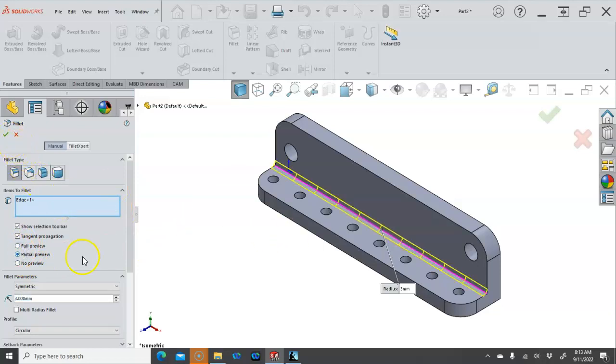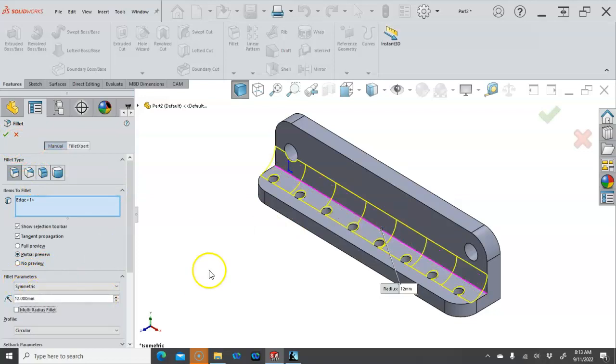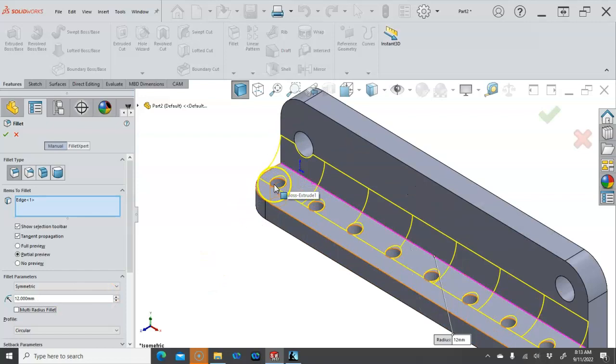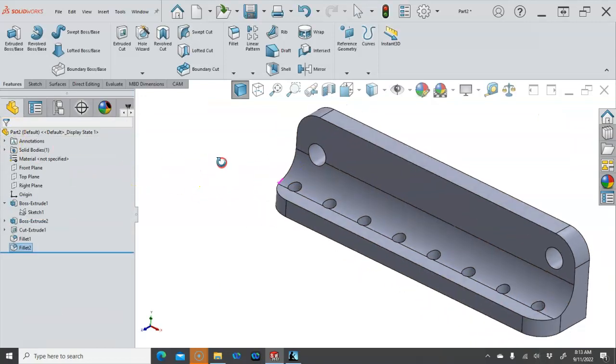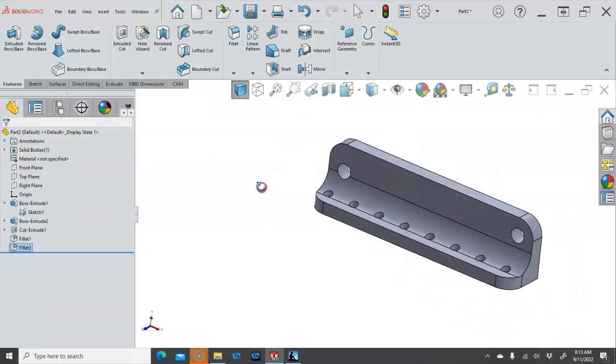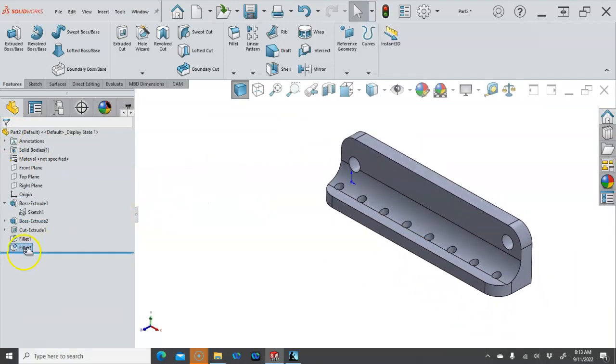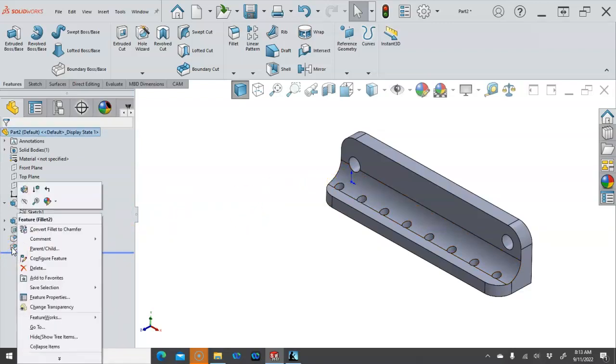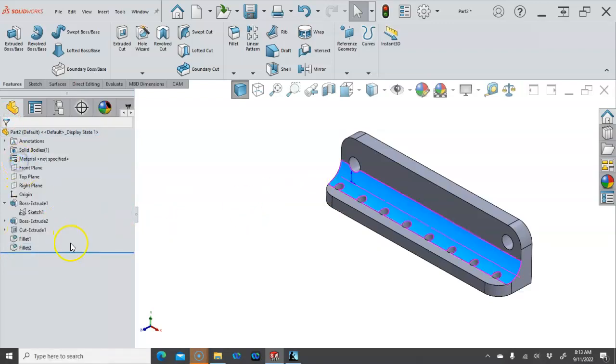Something like if it stayed at 10 or 12 would show us that it's going to have that intersection. Part of the problem here is we would maybe lose some of that hole geometry depending on how we drew this. So you always want to check and make sure that the hole is complete if you have that level of intersection.